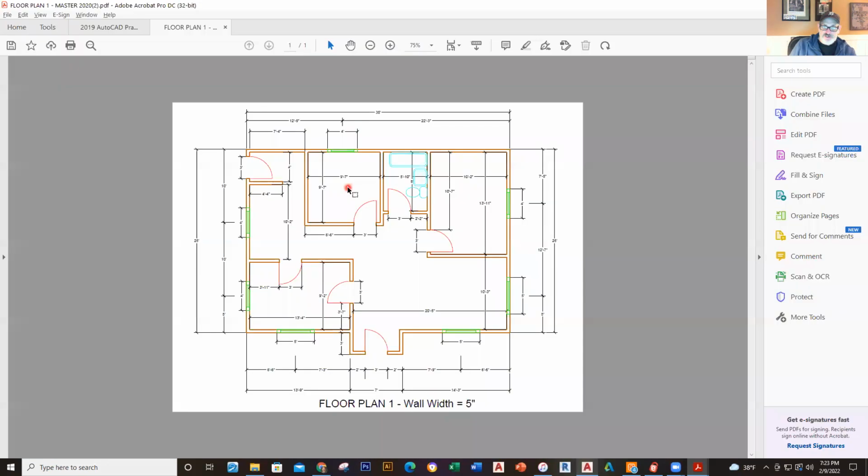Okay, now the next set of walls over here, I got this. Now this one, this is 7'4" inside to inside. All right, and then the actual length of this wall. So it goes 7'4" over. If I want to get the inside of this wall right here, which I could do because that's what these are, I can go 7'9" over because of the thickness of the wall, and then go down 9'7". That's what I'm gonna do. So I'm gonna go 7'9" and then up 9'7".